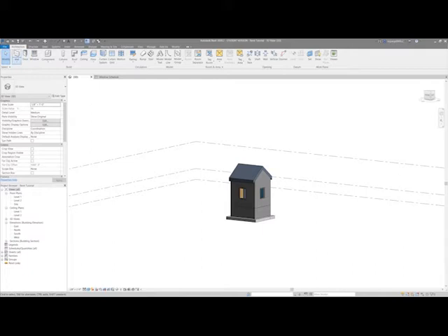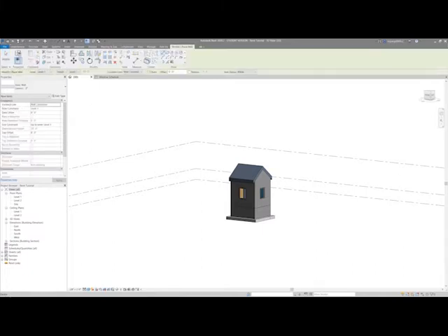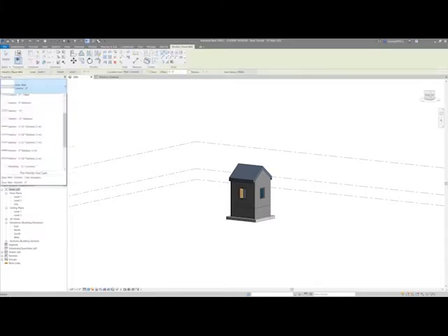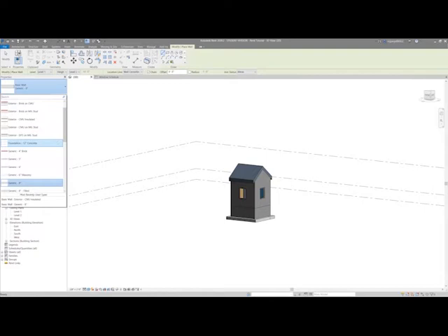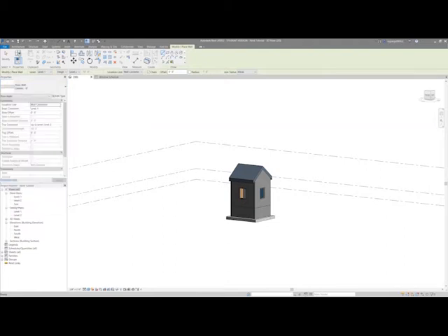So we're just going to start with a wall, and you have different choices of walls you can put up. This is what's preset into Revit with wall families. Those families are anything that holds information that can be tweaked. So we'll go with a generic 8-inch for now.